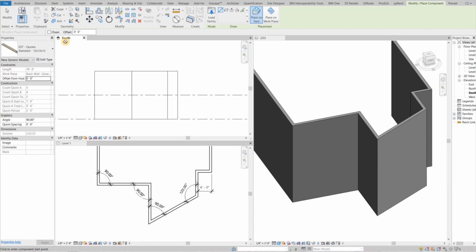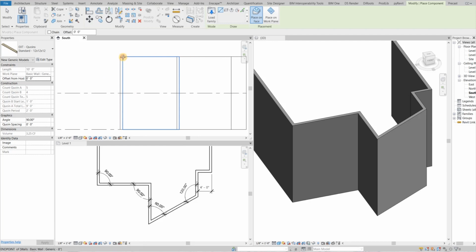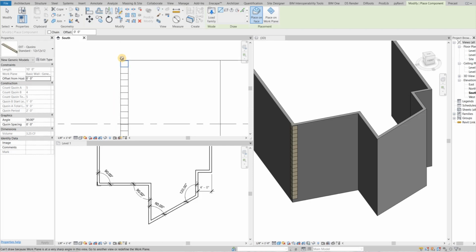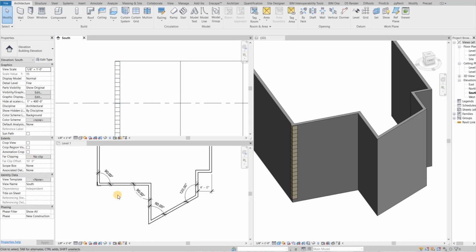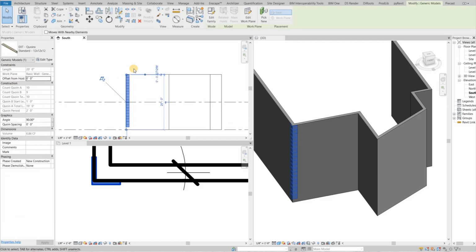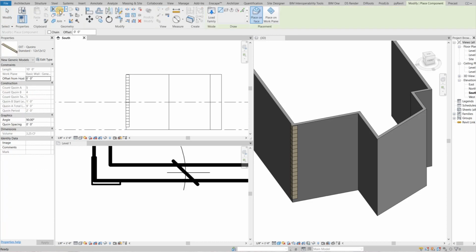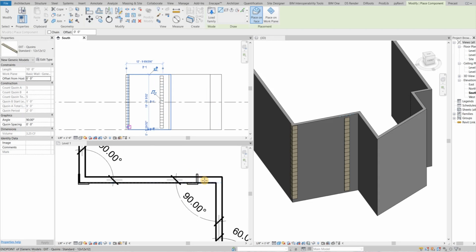Now here you need to just go to the south elevation of your wall references and start drawing on the face where you want to place it. This time I'm going to draw from top to bottom. As you can see, when you draw this Quoin family from top to bottom, it creates that leg on the left side. Since this is a line-based family, if you start drawing in the other direction, from bottom to top, you will see how it created this leg on the right side.